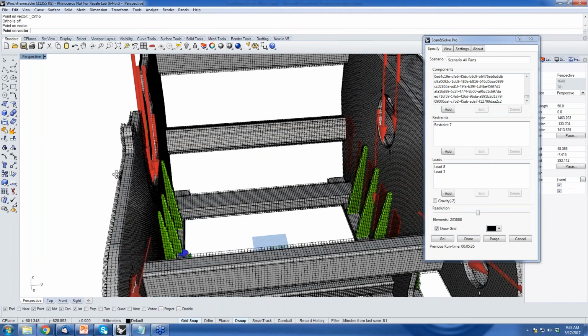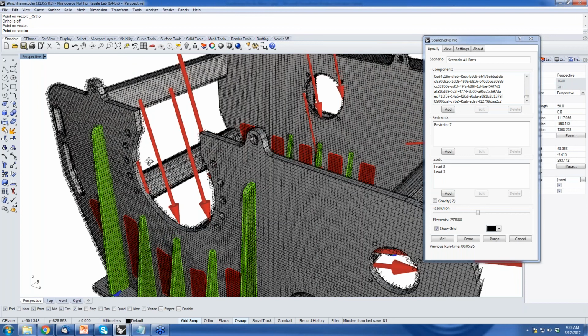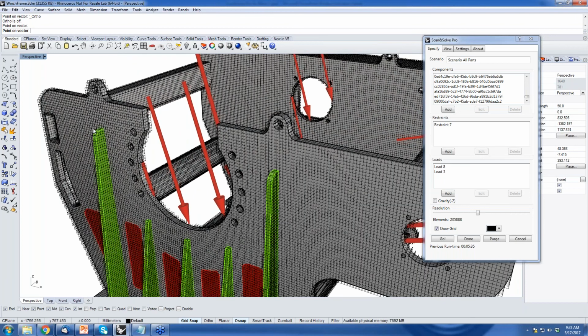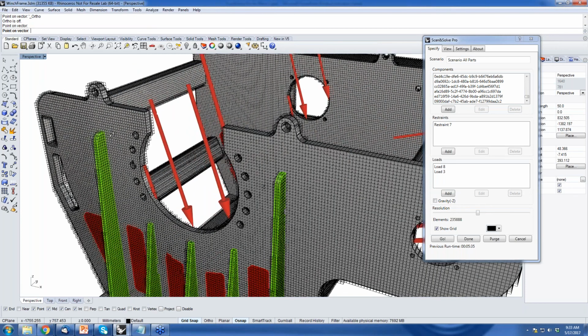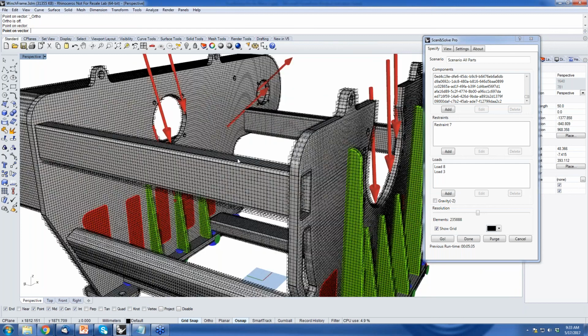If these individual cubes cross a boundary or cross an interface, then the objects that are included in that are considered bonded there. This is very related to the earlier question about how to handle different connections. So the only connections we have right now are bonded contact.